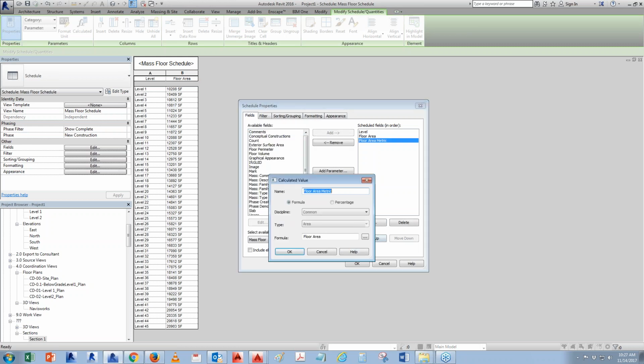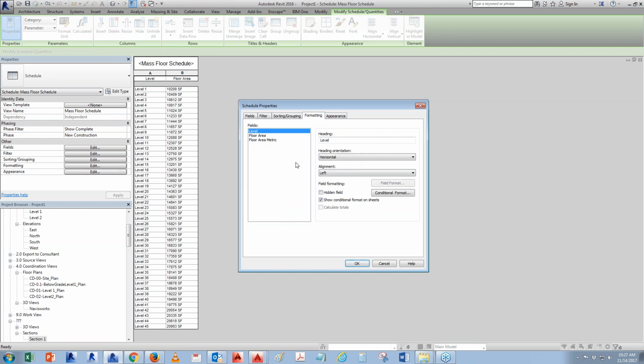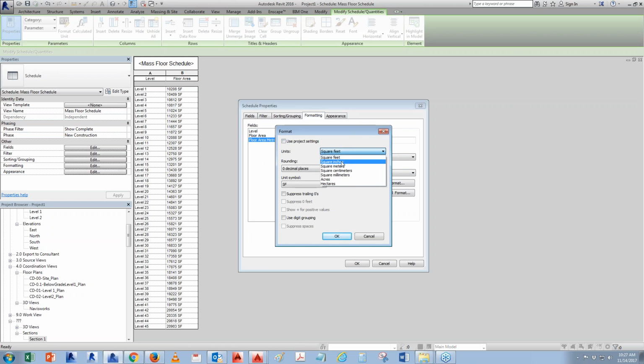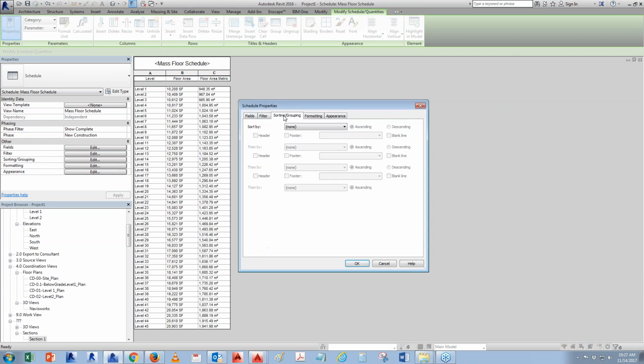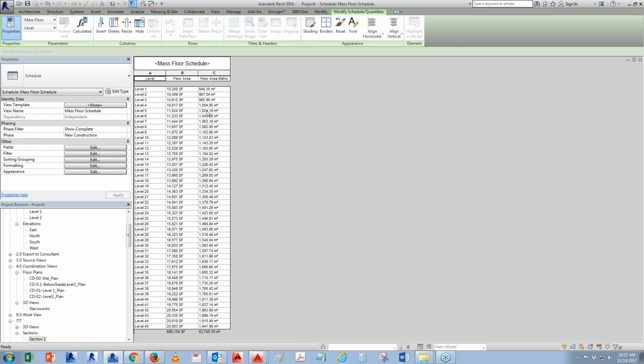Okay, and what you're going to do with this, same way how you do it, is calculate total, field format. Instead of using that, say square meter. This one I like to put in 2 decimal places and say okay. And what you do here is you can say grand total or itemize every item. That's fine. So total only. And what it does is it allows you to calculate how much floors you have. So it allows you basically to calculate what you have within your floor.